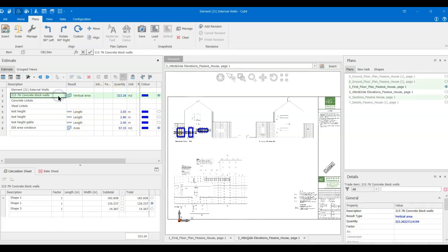So if I go back into this shape here, I'm deducting the area. Essentially, I'm doing 2 things at the same time. I'm measuring the length of my lintels when I go in and do the area measure. It gives me the length of the lintels before I add on the bearing. The bearing is on both sides, either side. And then I also have the measure for the deduction.